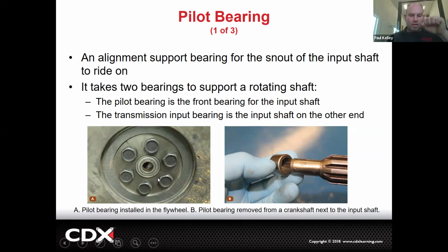And if you do it right and you smack that input shaft with a hammer, like if you make a little special service tool, you can actually hit inward, which will pressurize the grease and pop the bearing outward. Okay, that's one way to remove these, and it does work. We've done a couple videos on that.